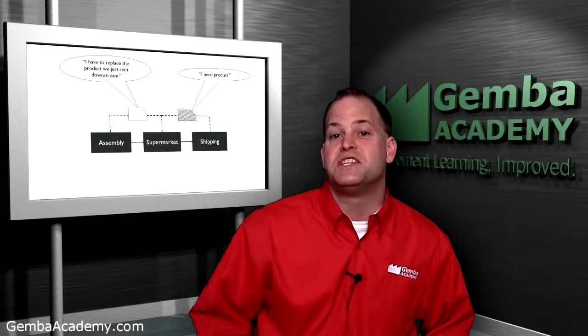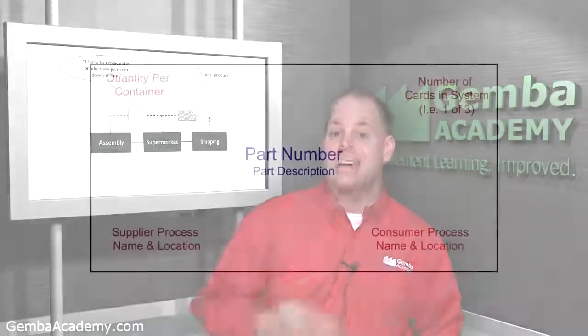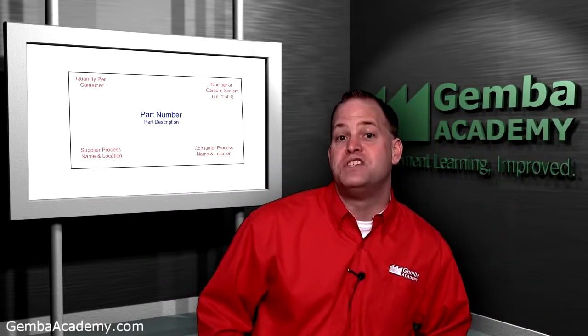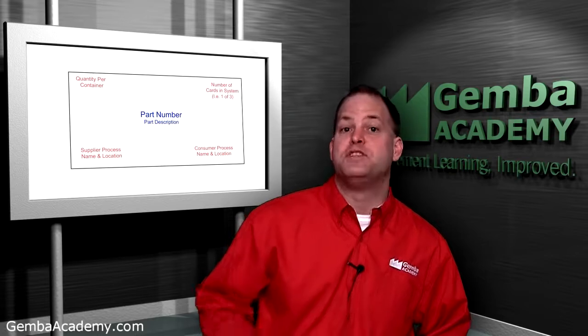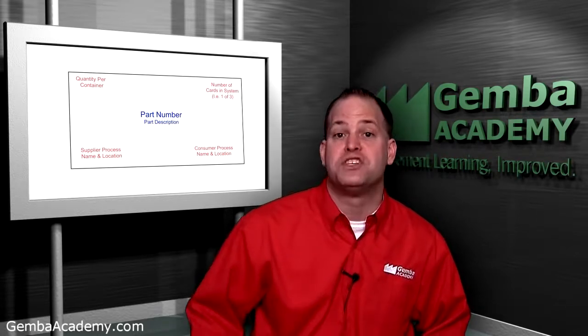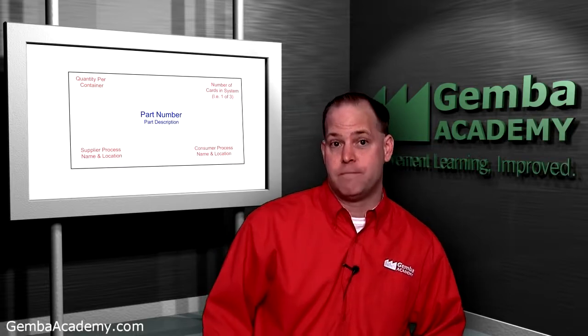Now, we'll get into this in more detail later in the course, but a Kanban card normally contains information such as the part name and number, the supplier process name, the quantity per container, the delivery address, the storage address, and the number of cards in the system. A Kanban system using cards differs most significantly from the two-bin system, which we'll discuss shortly, in that the card is pulled as soon as the first part is taken.